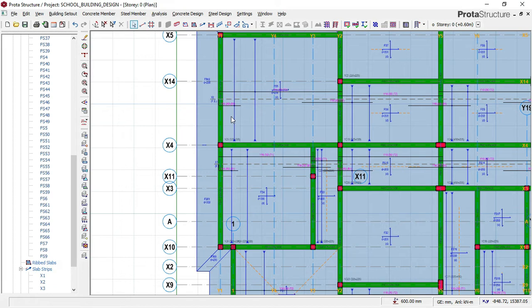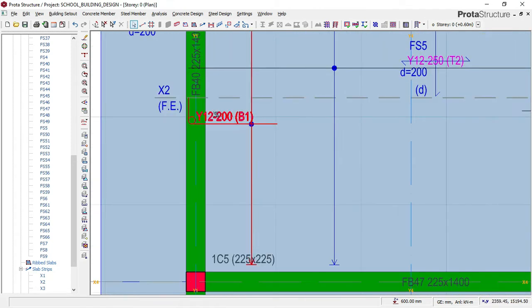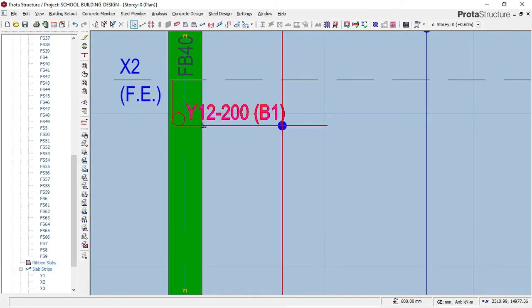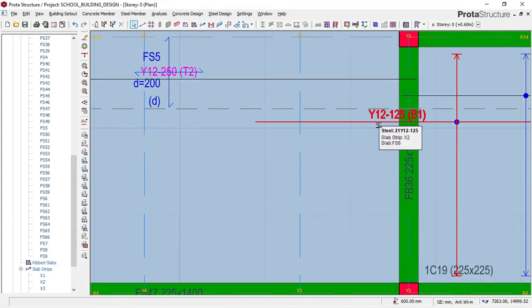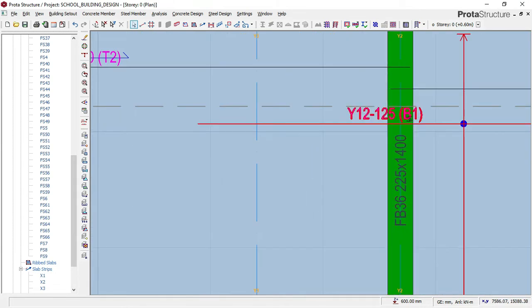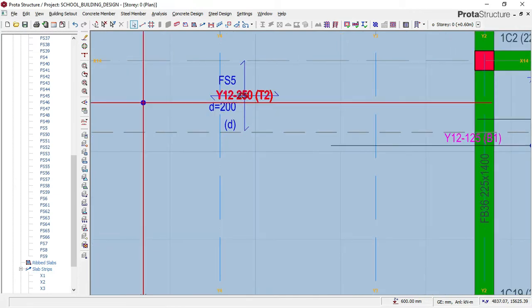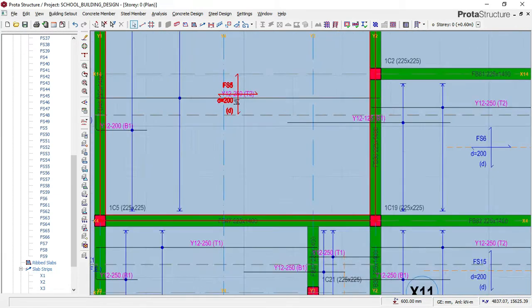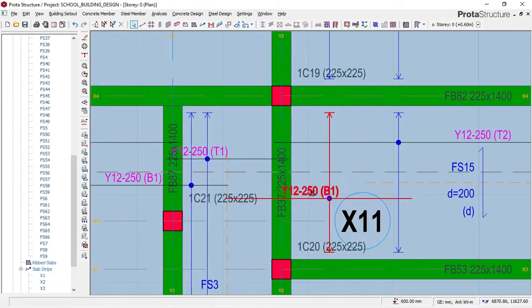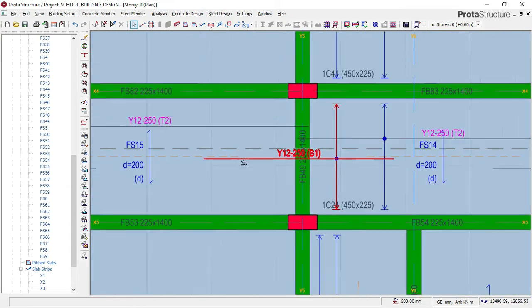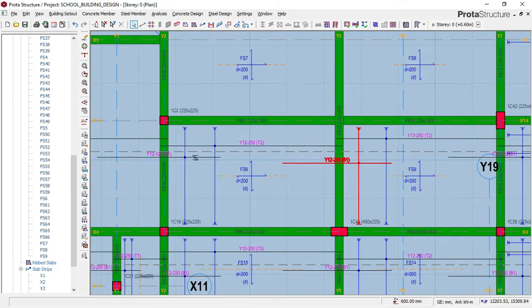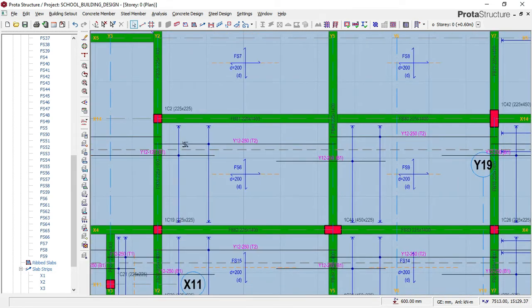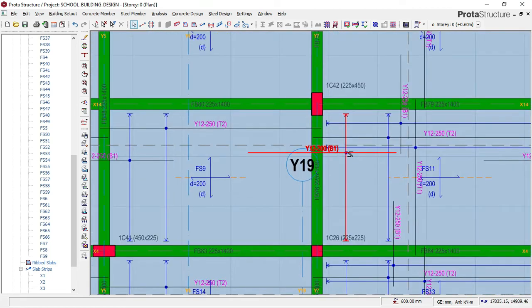Wait for it to finish up. It's still trying to load. Okay, now that's fine. So you can now see that it's now showing us Y12. So you can now see that all our slab reinforcement for the Raft Foundation is giving us Y12, and some parts spacing is 125 and some is 250. Although we can use 200 here on this place showing 250. Almost every part is showing 200 except this one that we saw here, which is that 125 here. Okay, that's fine. So we have to take note of this here, and then take note of this. Okay, this one is 200.